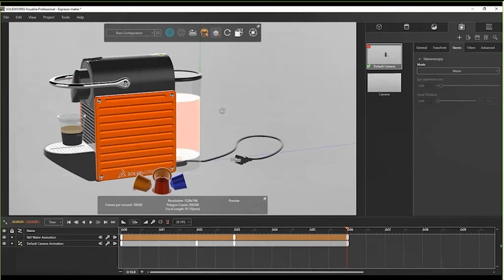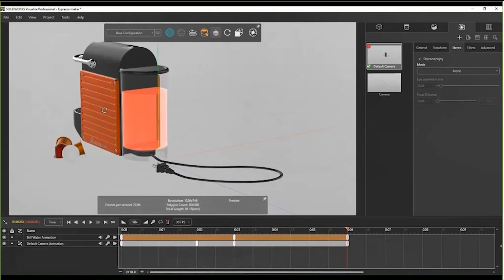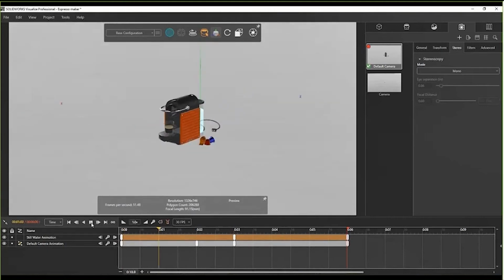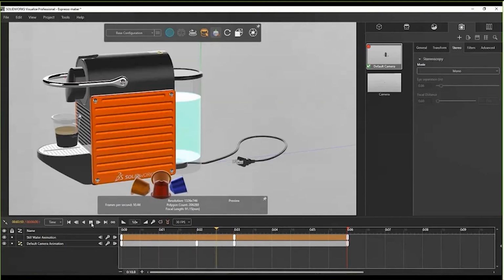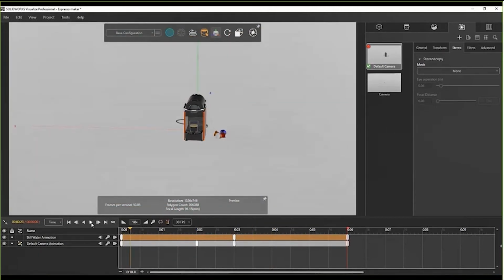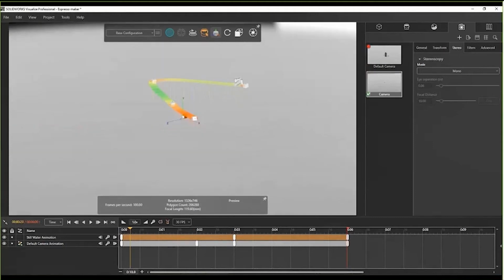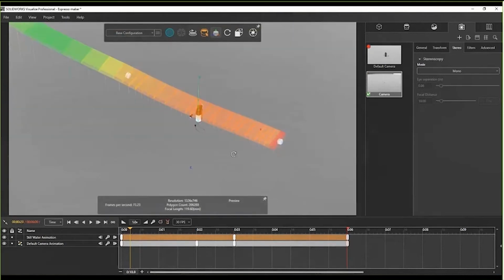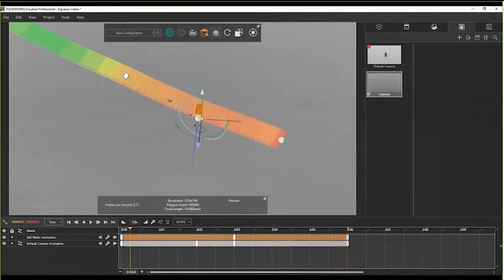And then over that last 3 seconds, let's do another 180-degree turn, okay? So as we play through it, that's not exactly what I wanted, right? So that's where I needed to add additional keyframes, and this is where that second camera is extremely helpful, because you can see the entire path that camera is supposed to be going from my second camera.